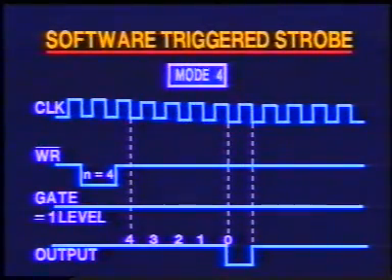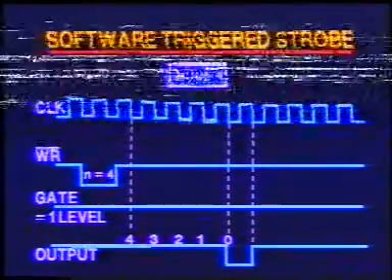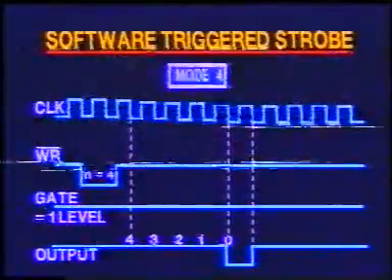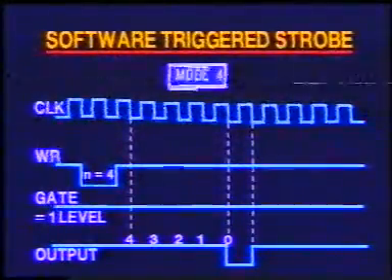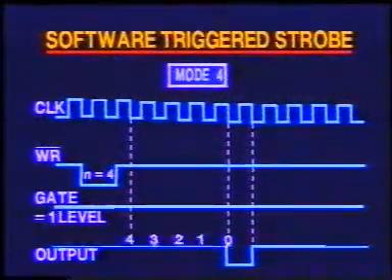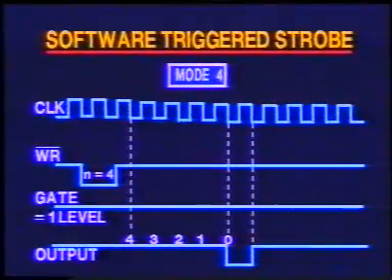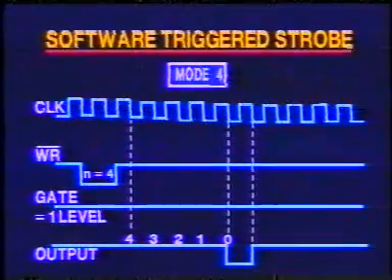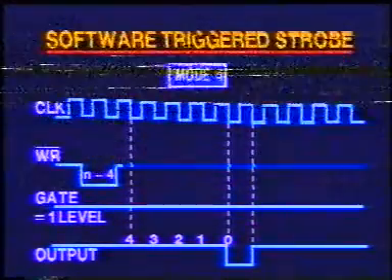The gate signal may be made to disable the counting. When counting is on, if gate is made low, the clock pulses are ignored and thus counting stops. The counting resumes when the gate is made high. Any change in count value becomes effective after the present count is over.